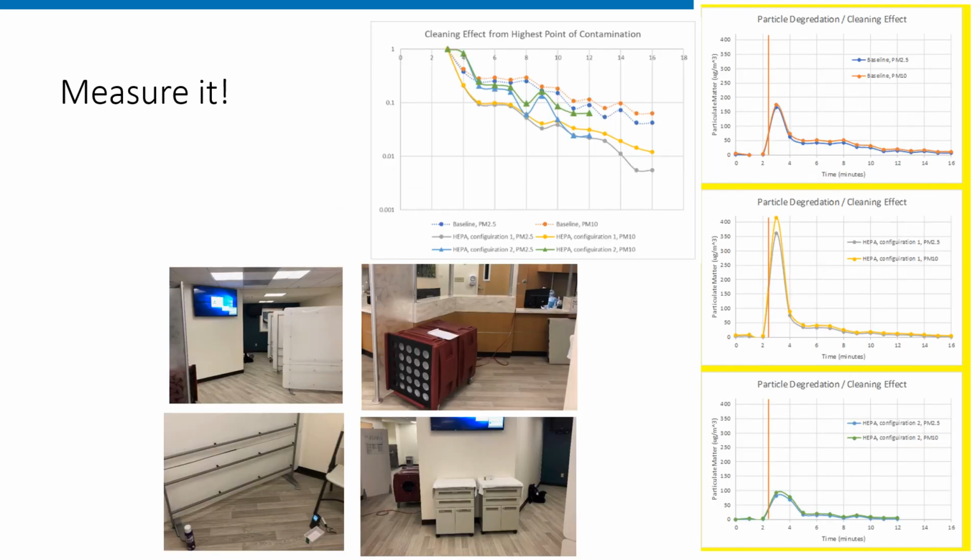This is a screening area with a 1,000 CFM HEPA filter unit blowing clean air around the space. So to test this, we fouled the area of one station with a 10-second spray of Aquanet hairspray. Baseline test without the HEPA showed 16 equivalent air changes. That's better than it should be. The space only really has 6 air changes. And then with the fan on, it went up to 20 to 25 equivalent air changes. So it went up about 5 to 10, but it should have gone up 15.